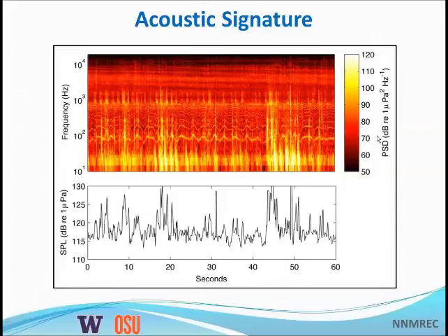Rather than integrating over the entire range, we've chosen to integrate above 60 hertz because after manual review of most of the data, we could find no evidence of significant noise from the device below 60 hertz. Looking back at the spectrogram up top, what we see above about 100 hertz, going up to around 1,000 hertz, is a number of harmonics that modulate frequency with time. If you take a closer look at those frequency modulations, they occur on approximately the dominant wave period.